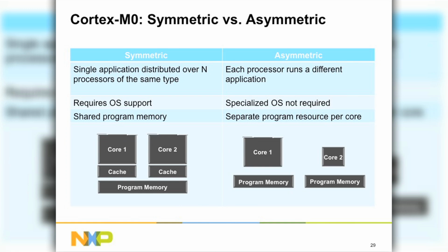And what that gives us is the ability to have the M4 be completely focused on signal processing or whatever task you might be looking to do, and have your M0 handle all the I/O capabilities. So now you have the M0 ROM drivers, as we talked about. The M0 can be handling that, and you get the M0 chugging away at USB or Ethernet, so you don't have to be bothered with that as you're programming the M4. So it gives you more capability, and it should actually simplify your design as you partition things, as you start to add complex peripherals like USB and Ethernet.